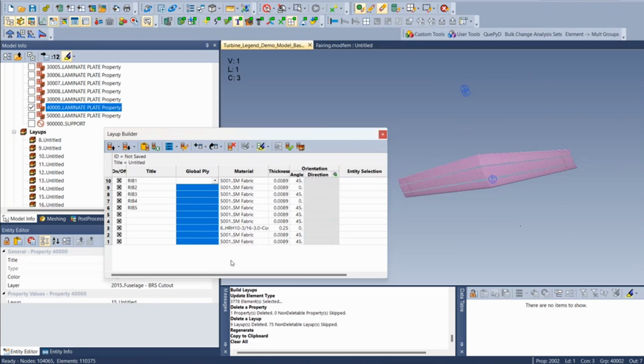The thing I would always use global plies for is plotting. So if you had a core that spanned multiple layers, because you have different advances and things, and you want to look at shear stresses on that core all at once. Yes, I definitely see the usefulness of it. Our team, and I don't know if any of the rest of our group has used global plies too much, we just have not pushed it yet. It's probably something I'd like to integrate into our workflow at some point.